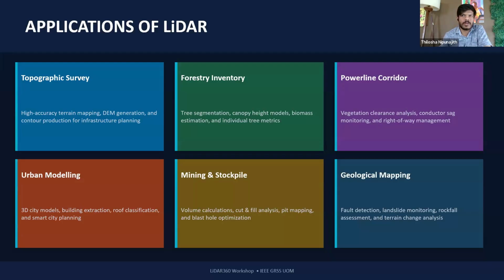Doing this through conventional, traditional surveying work is quite time consuming and has many practical issues. So what you can do is rely on scanning technologies like drone-based LiDAR scanning or mobile-based LiDAR scanning, or you can rely on drone images as well. But when it comes to drone imagery, there are obvious things that you can't cover properly from an aerial image.